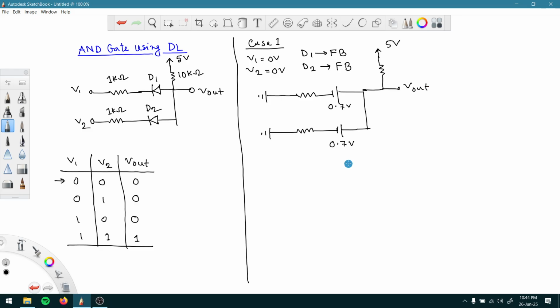So how can we simplify this? We can again take the assumption that these two nodes here have the same potential because of these two voltage sources being similar voltages. So that means we can just connect it here, and you can just omit these two voltage sources with just one, right? So let us try to do that. We will try to simplify that. Also, you see both of the grounds can be shorted together. That can be done. So let us try to do that as well.